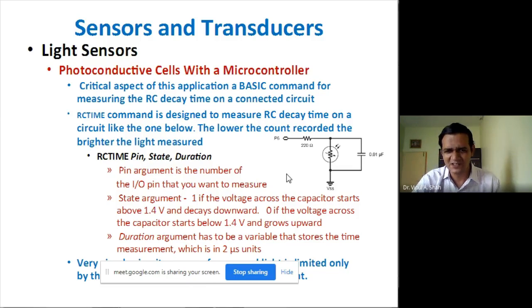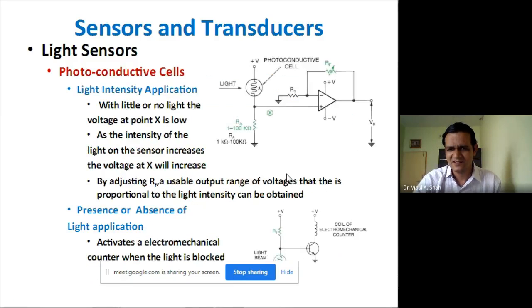There is another circuit through which we can monitor and maintain this light sensor. This can be applied to the microprocessor based system here. Say, for example, if you want to convert that, we can have the display of it. So this is my analog circuit. We can have the analog to digital converter of this voltage output. So we can provide one ADC circuit here, which will be converting this voltage into the digital signal, and then we can apply it to the microprocessor based system.